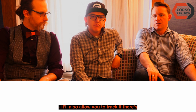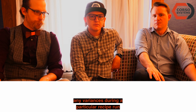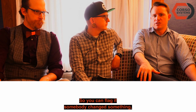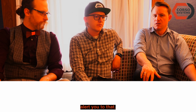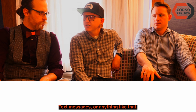And it'll also allow you to track if there's any variances during a particular recipe run, if any set points are different than what they are in the recipe. So you can flag if somebody changed something, or if there's a set point that's different than it should be, the recipe module will alert you to that. Yeah, and we can send out alerts with that, text messages or anything like that.